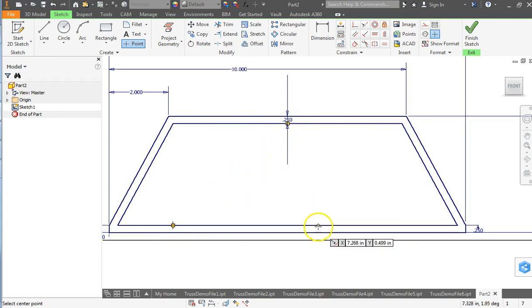For me, I know I wanted one at the midpoint. If you hover along a segment with the point tool, you'll eventually find the middle. It lights up as a green dot. You also see, look down and right from my cursor, and you see the little gray box with a dot to a line with a red dot on it. That lets me know I'm finding the middle versus just getting the point on the line here. So that symbol changes when I'm at the midpoint. So I'm going to click there.